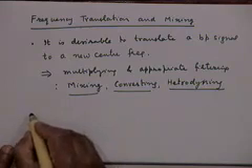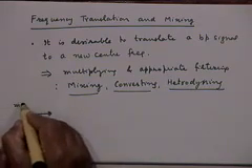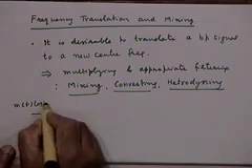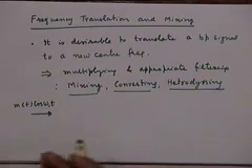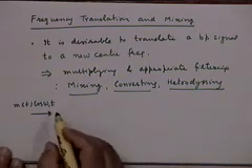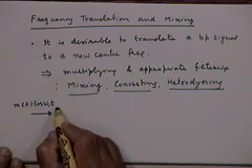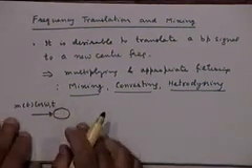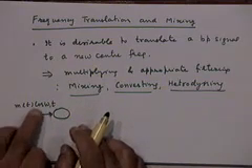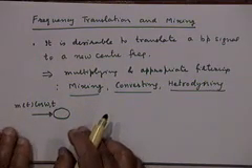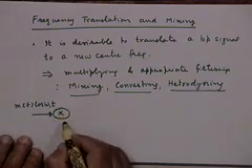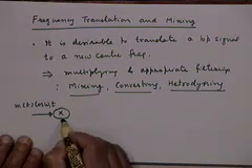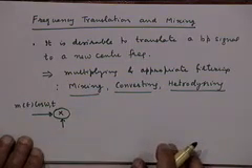So what we are saying is, you have a bandpass signal, let's say m(t) cos(ω1t). For the sake of simplicity, I am taking only the in-phase component, but you could take a general bandpass signal with a general representation, without any loss of generality. So I have taken a bandpass signal m(t) cos(ω1t). Where is it centered? ω1, right? The center frequency is ω1. Let's say I want to translate this to a center frequency of ω2. What should I do?